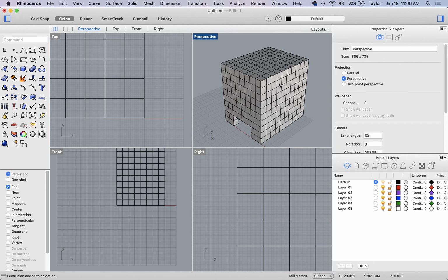So hopefully you get the idea. So through these commands, you should be able to make more complex stuff. If you're interested, you can make like a little spire. You could make a roof at a 45-degree angle by just typing in a different number of degrees in the rotate command. Now is when the creativity takes over. And I know we haven't seen a lot of techniques yet, but this limitation will really help you get used to some fundamentals, which we'll build on after you do this practice assignment.